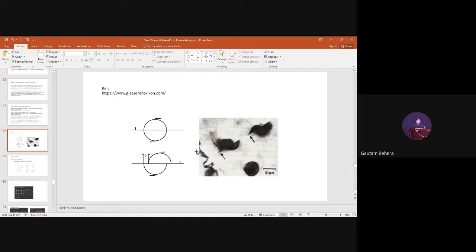So what is happening? You can see the next stage. Can anybody tell me? Cutting, very good. So the dislocation will cut the precipitate into two halves. This is one half and this is another half. Now carefully look at this image and tell me what is happening to the surface area and surface energy before cutting and after cutting.